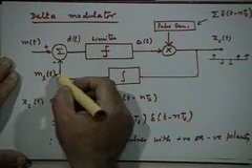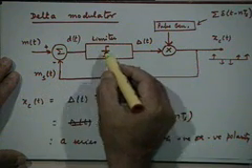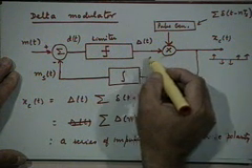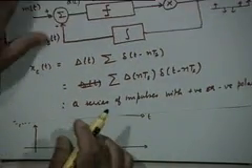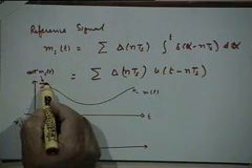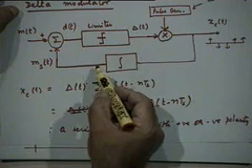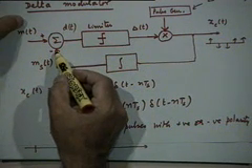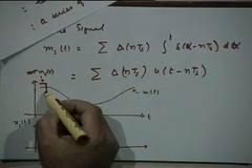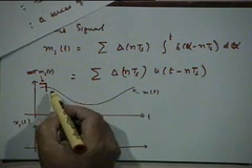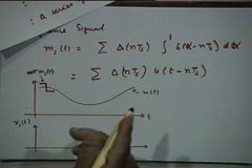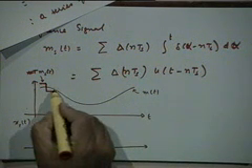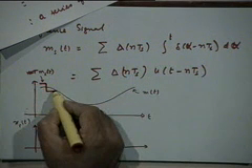This was less than this, so this was negative. After limitation, this becomes -1. This produces a negative impulse. This negative impulse, after T_s seconds, at this time instant produces a negative step after integration, and that negative step now modifies the reference signal from here to here. Is that clear? And now this value will be held constant till the next impulse, till this changes.